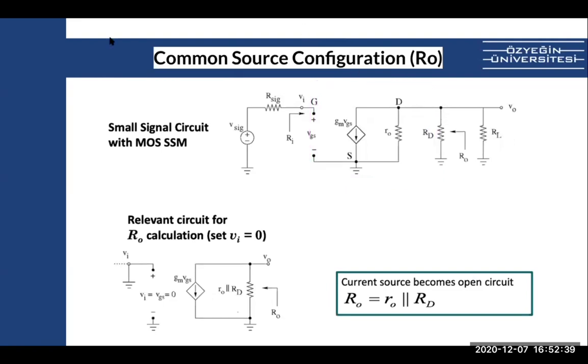So now we are looking at the circuit from the output. And this is a load. We don't really care about the load resistance because we care about whatever is there other than the load. So we look at the output impedance. And when we do that, remember, it's just like finding the equivalent resistance. It's the same logic. Well, it's actually the same thing. When we were finding the RTH, that's exactly the same thing we are doing here right now.